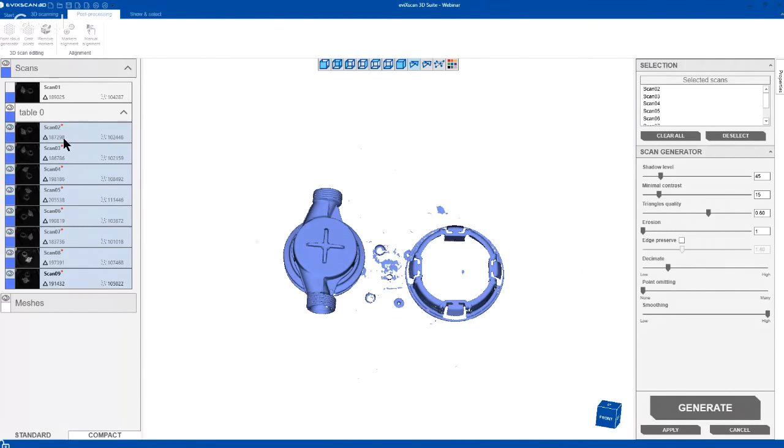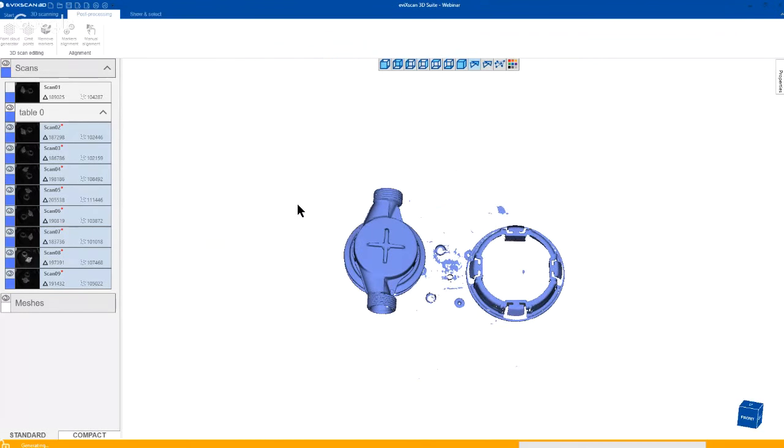As you see, on the scans we've got not a large volume of triangles because I was using the decimation, the intelligent decimation option, the algorithm, which is parametrized by allowable deviation. When I change that to 0, I will have raw scan data without any decimation.